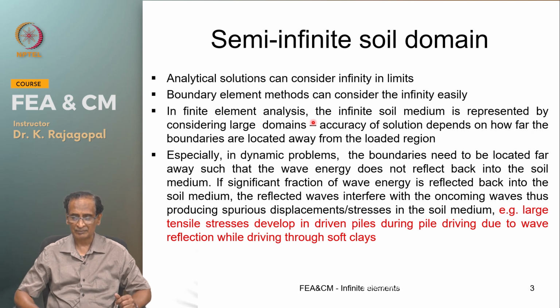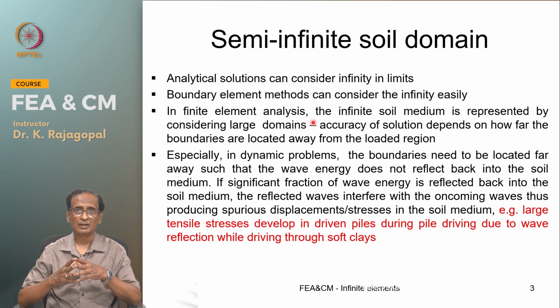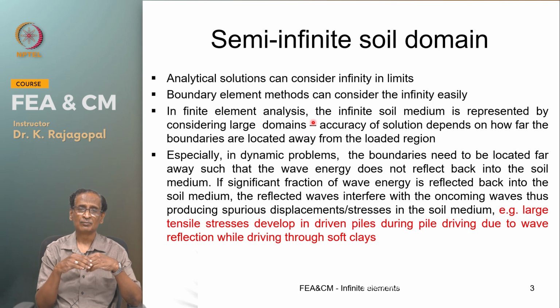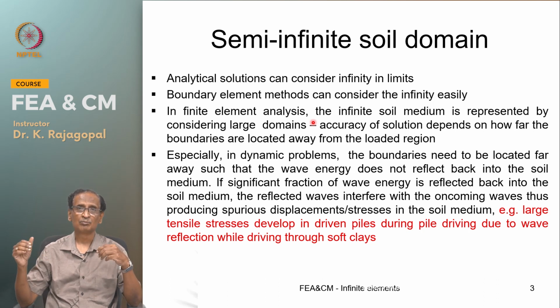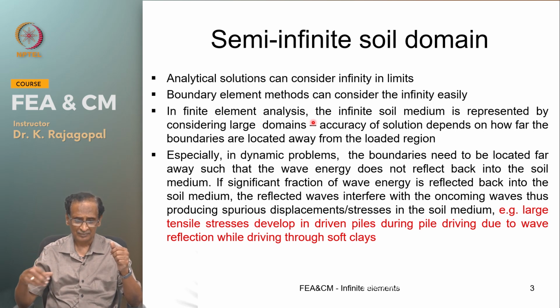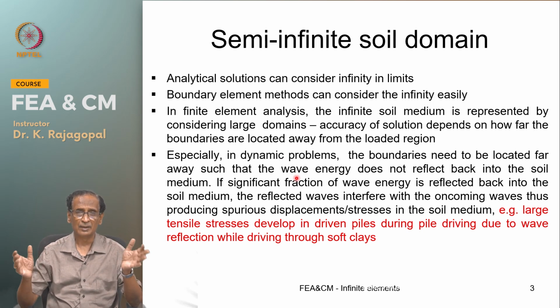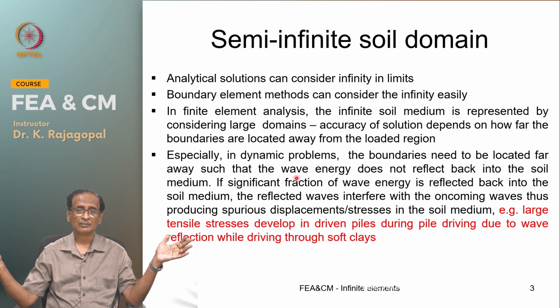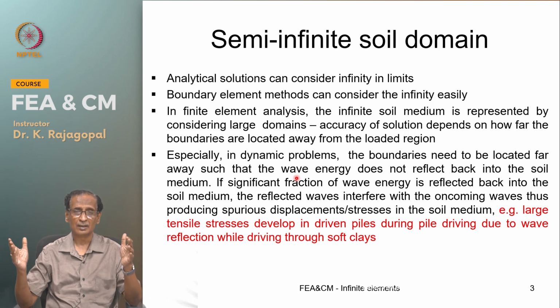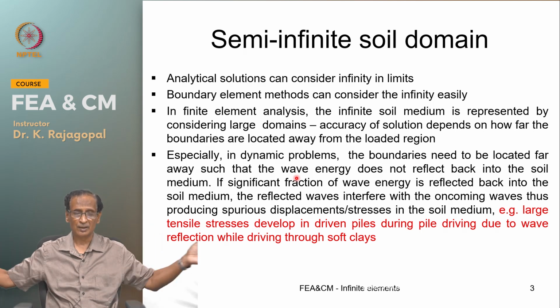And some investigators tried combining finite elements and boundary elements, because the boundary elements are good in representing the boundary problems, and the finite elements are good within the finite region. When we deal with any dynamics problems, the boundary plays a very important role. If you place the boundary too far, then your computational effort could be very high, because instead of having let us say 1000 degrees of freedom, you may be having 10,000 degrees of freedom, because you have additional number of elements.